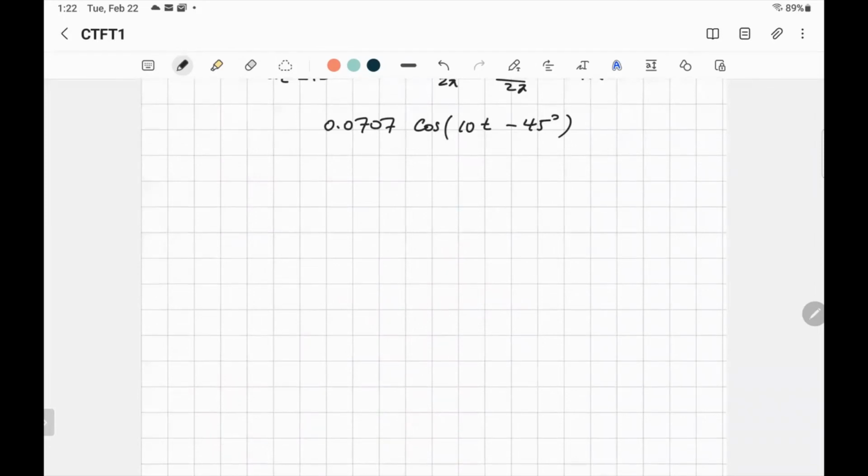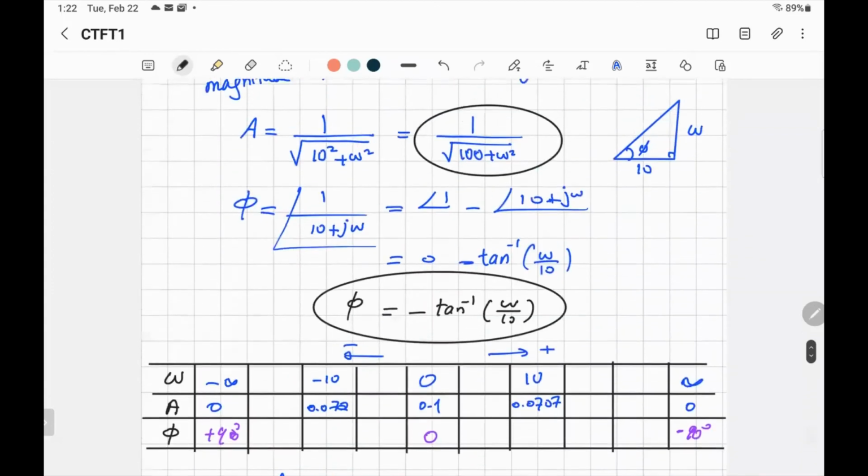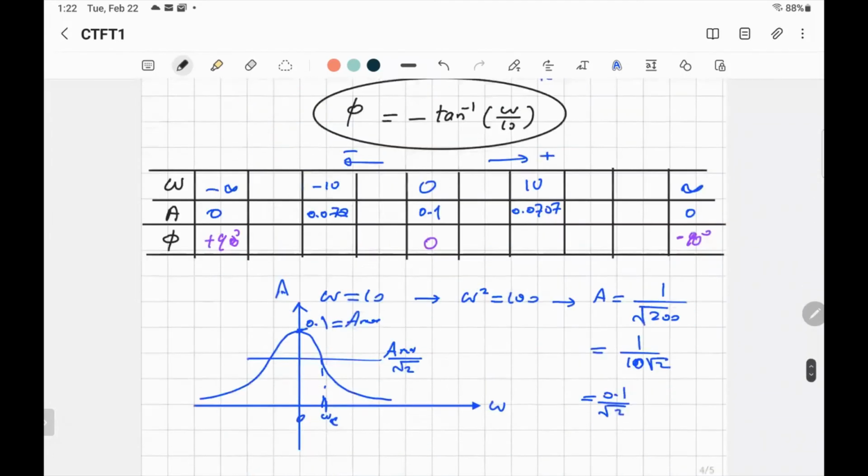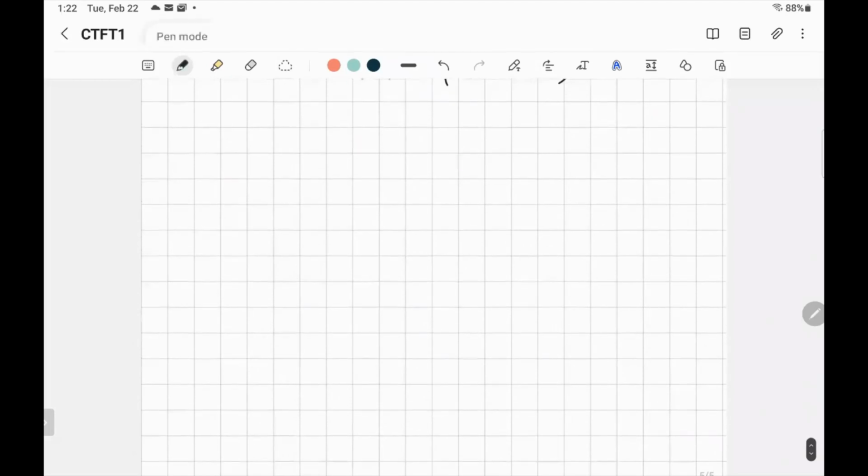Of course, the Fourier transform that I just explained, that's the general expression that I used, that's very famous: integration from negative infinity to infinity of x of t times e to the power of minus j omega t, and it'll be complex in general. Then they said, okay, complex, what about if I can express it in rectangular form? Because complex means there is a real part and an imaginary part. So I want to divide it into two parts. Well, let's see how we divide it. So let's say now, express the continuous time Fourier transform in rectangular form.